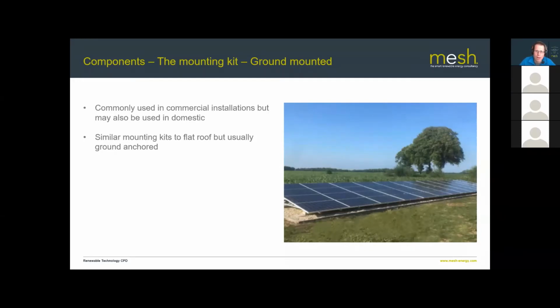Mohammed asked about solar panels that track the sun. As a general rule, they work very effectively. They're very high efficiency. The downside is obviously you're adding a huge amount of complexity to the system for a tracker, and generally speaking, from an economic point of view, the added complexity doesn't pay back in the additional output. So in the UK, putting tracking in just doesn't make economic sense, which is why you'll see that almost all solar farms have fixed panels.